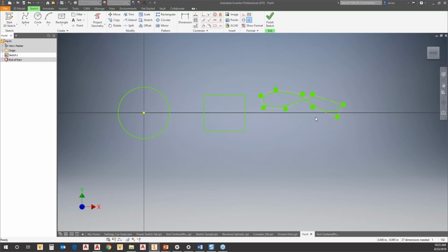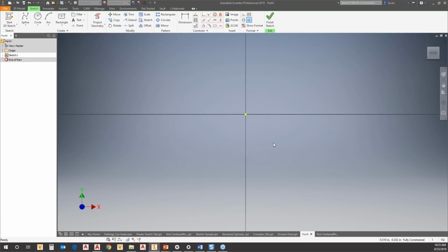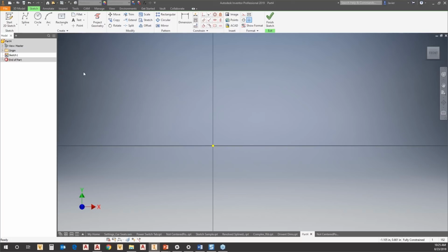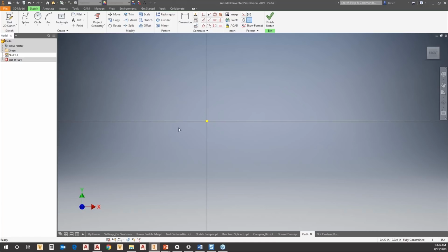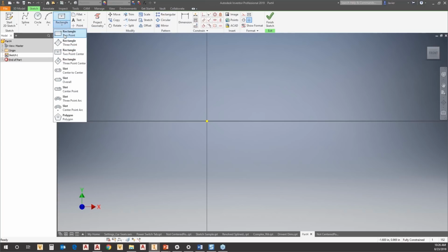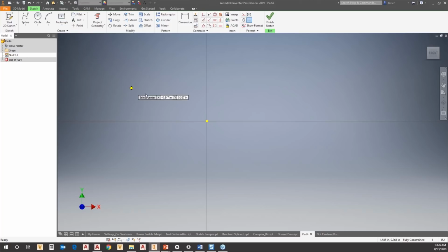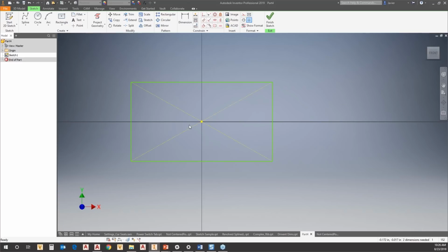Okay. I'll jump back to this. We were talking about centering your sketch. If you do have an unusual shape, unusual shapes are a little more difficult to center in a sketch, especially if you want it perfectly centered. So let's say instead you create a rectangle and center that. So I'm going to create a 2-point rectangle. This is obviously centered. This is not really what I want necessarily in terms of what I'm going to extrude. So something you might do is build inside of that rectangle.